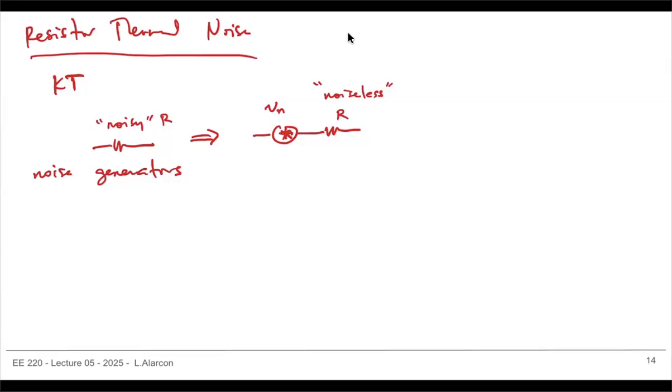What we normally talk about is noise power. That's like your signal to noise ratio, a signal power to noise power ratio. So the way we write this out is not the voltage of the noise, but the mean square of the voltage of the noise. And we'll talk about this in a bit. But ultimately, what you want is noise power. So I'll take each noise component, square that, and take the mean. So it's the mean square of the noise.